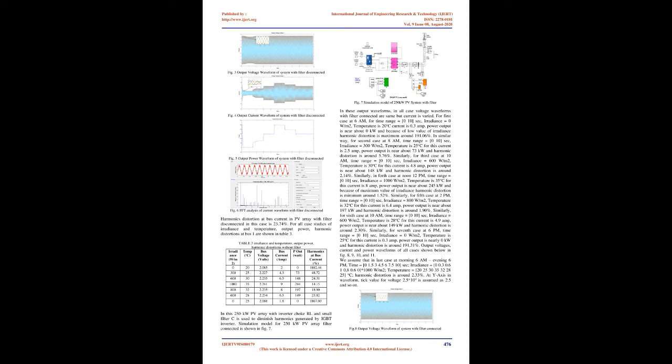In this work, to extract the fundamental and harmonic distortions in current signals, FFT analysis is used. Much research work has been done using pulse width modulation, PWM, techniques to mitigate harmonics. 4. Simulation result. This system consists of a 250 kW PV array connected to power switching devices, IGBT, and inverter control, which consists of MPPT, PLL, PWM modulator, current regulator, DC voltage regulator, etc. The converter is modeled using a PWM controlled IGBT bridge. A 250/25 kV 3-phase transformer is used to connect the inverter control to the utility distribution system.